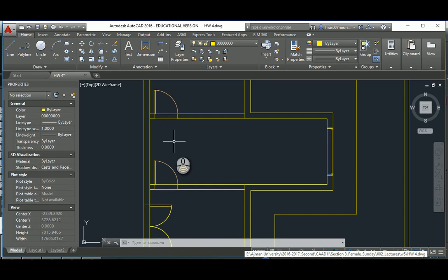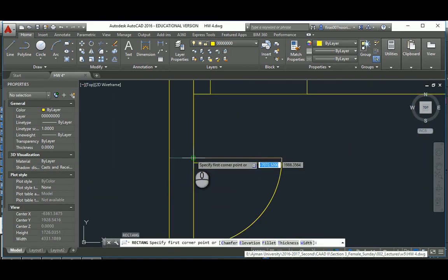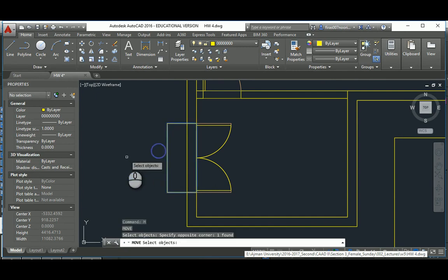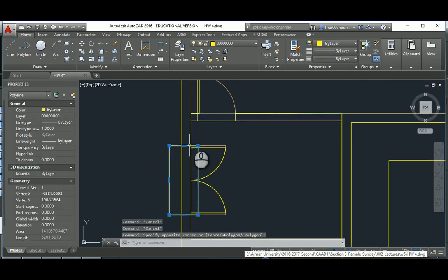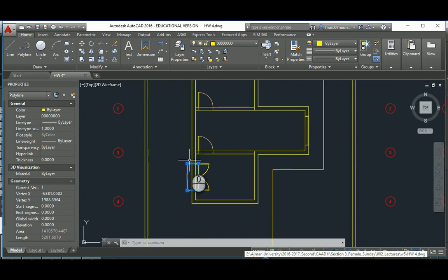Let's get this finished. So I'm gonna do this rectangle for the door. I'm gonna click here and then hover above, putting my mouse above this without touching it. Move my mouse to the left using polar or ortho, I think, to the intersection. Move this rectangle that way. This represents the box that I'm gonna cut off from the exterior wall, representing this double door. It should actually be bigger than the wall. That's why I created it from this point and then pushed it that way. That's for the wall. So right-click block again,